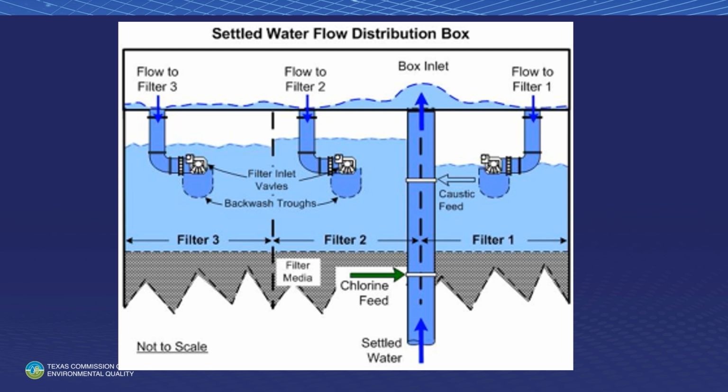Water coming up through that plant was laminar flow. Again, no internal mixing to speak of in that pipe. And when they had installed those injection points, they just went in there, and there wasn't a stinger in there. They just bored a hole in the pipe. The opening in the pipe was just flush with it. The water coming up here, they injected the chlorine here, but there's no mixing.